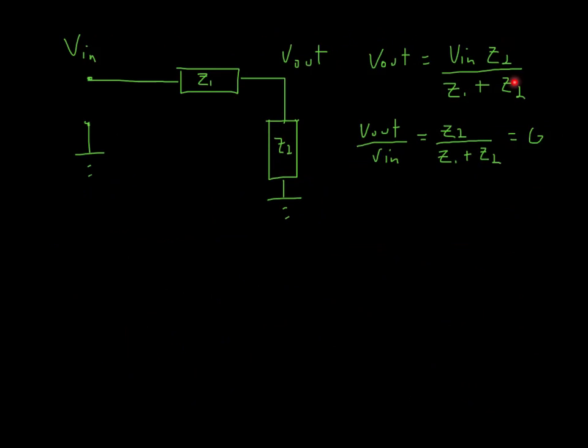And then there's something that's going to be more interesting to talk about, and that is, let's divide both sides by Vn, and we're actually going to get the ratio of V out over Vn, which is commonly known as the gain in electronics and other fields as well. Alright, so in these passive circuits here, the gain is always going to be at best 1. So at best in the voltage divider, as you know, if Z2 is a very stiff load, if Z2 is much, much bigger than Z1, V out will equal Vn, and then the gain will be 1.